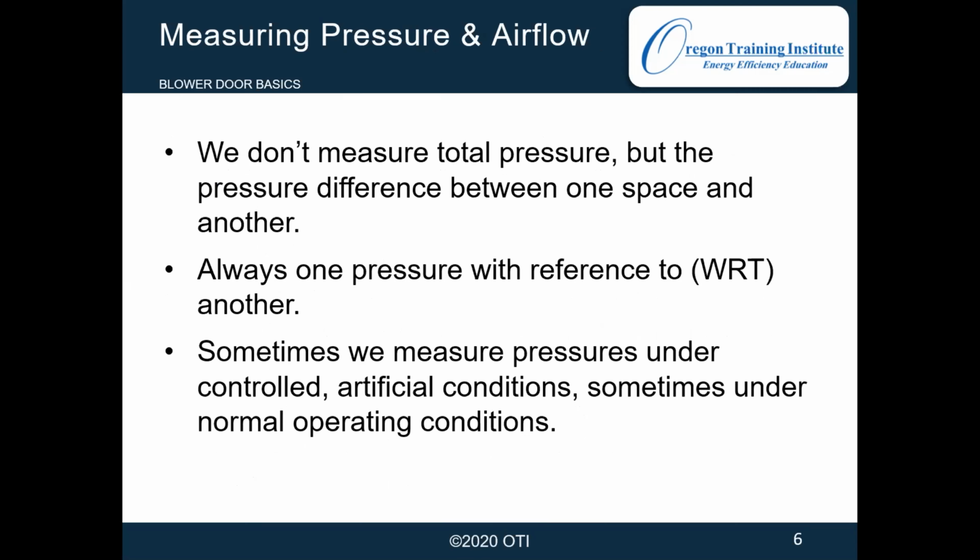So the manometer, it doesn't matter what kind of manometer it is, all of them measure one thing, and that's what makes them a manometer. A manometer measures pressure. Most of our manometers are dual channel, so it's 2-in-1. There are some single channels, but they're not very popular in weatherization, though you might see them in HVAC. So our manometer: dual channel, measuring pressure.